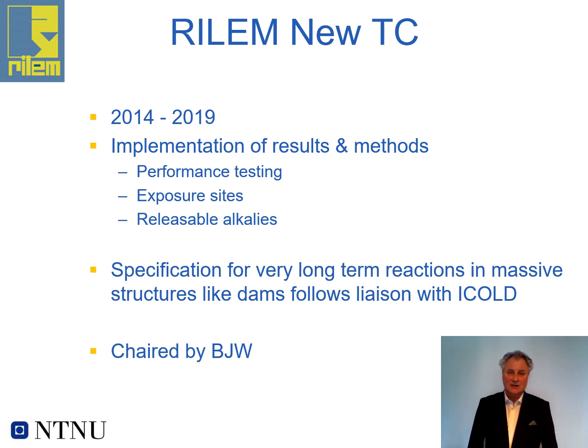And now in April 2020, we are submitting new test methods about alkali release called AAR-8, a new performance test method with the bigger concrete prisms called AAR-10, and also versions with a higher temperature at 60 degrees called AAR-11 and AAR-12, and also an approach where we are wrapping the prisms with some alkali to compensate for the leaching called AAR-13.